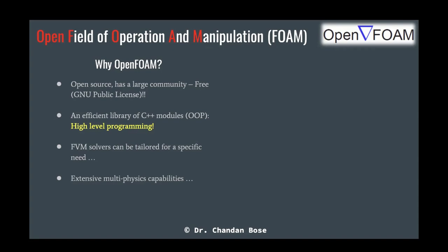You can write your own solver. That is the best advantage of using open source tools, and it has extensive multi-physics capabilities. It has cross-platform coupling like FSI, which means that you can couple OpenFOAM with another third-party solver. Like, for example, I showed you yesterday, you can couple it with other solvers. So it has cross-platform coupling.